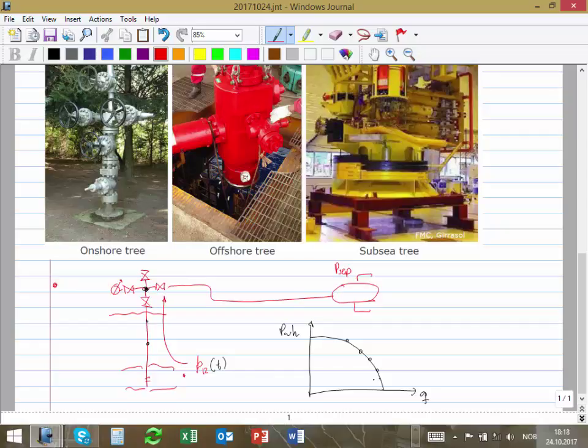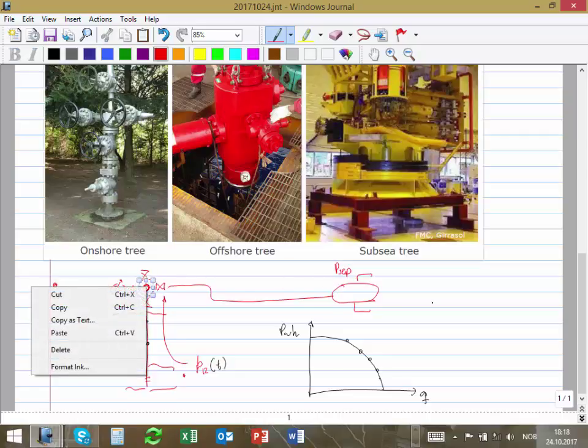So that curve in black includes IPR, includes tubing. If I have some other thing inside the tubing, like a restriction or a scaling, something that reduces diameter, I have to include everything in that curve. So I have to have a model for everything I have there. And then I want to calculate the required pressure from that point to flow against separator pressure.